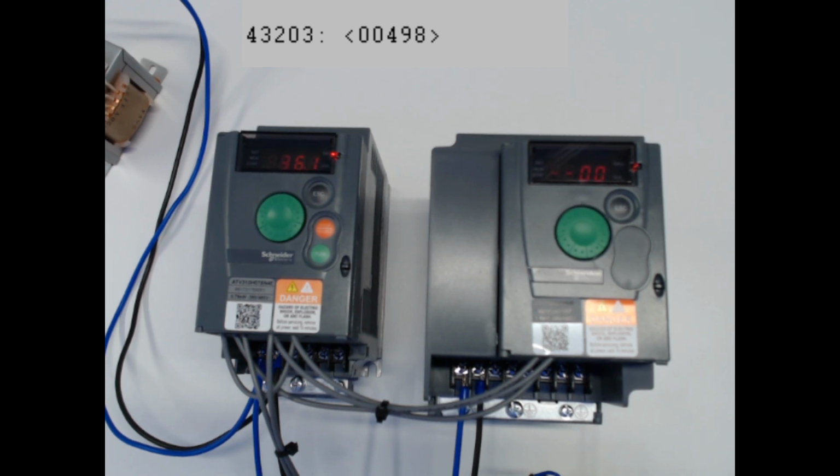So if I want to speed up the process, I simply drop it further. Now you can see that it starts to pick up very, very fast. And once it is at 50, the aux comes in, and you can see that it drops to 30 before going up again. So now both pumps are running at the same speed. It's a bit hard to see due to the flickering, but from my side, I can see that at most they are 0.1 hertz different. 0.1 hertz is quite negligible in terms of the pump.